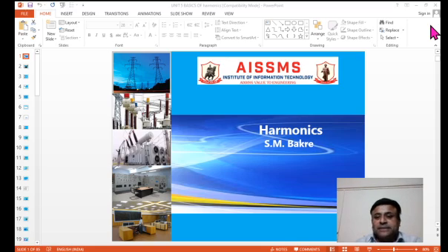You will observe that there is a flicker in the voltage, there is some sort of distortion in the voltage. At the same time, the current waveform is also distorted. So this is because of harmonics. The presence of harmonics distorts electrical signals. Therefore, power quality is affected because of the presence of harmonics. And therefore, harmonics has been considered as an important topic in PQ.